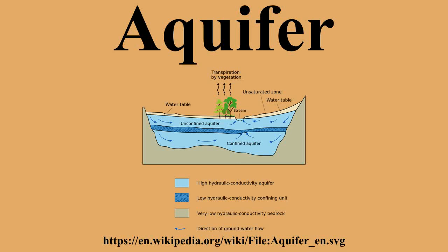Multiple wells for one water supply source are termed well fields, which may withdraw water from confined or unconfined aquifers. Using groundwater from deep, confined aquifers provides more protection from surface water contamination. Some wells, termed collector wells, are specifically designed to induce infiltration of surface water.